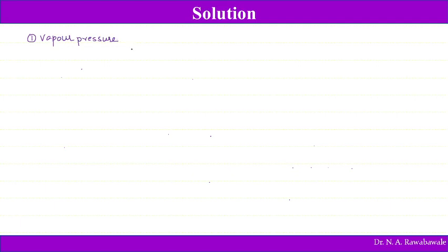So to find out vapor pressure, phi is equal to PV divided by PS. So to know PS at dry bulb temperature equal to 22 degrees Celsius from steam table, we get this PS as 0.02642 bar.